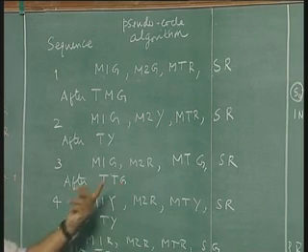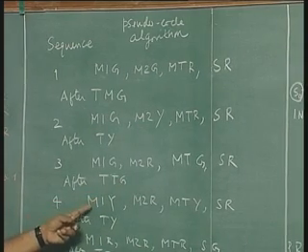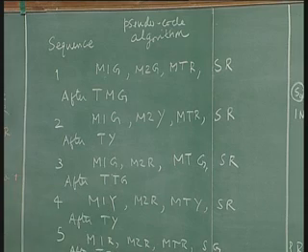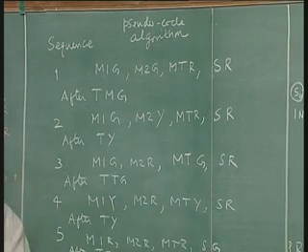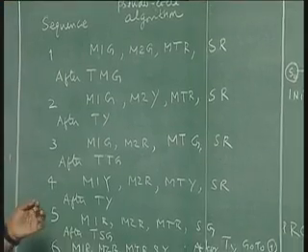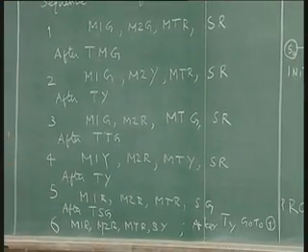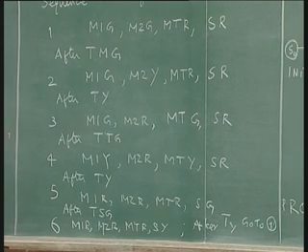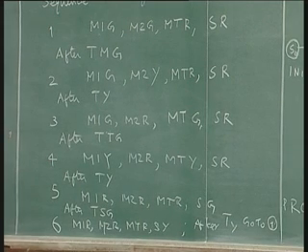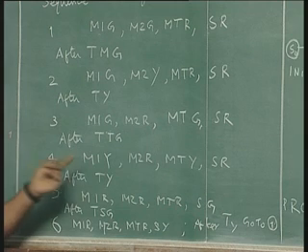After the elapse of TTG, I have main 1 yellow, main turn yellow. I am going to stop the traffic from left to right on the main state and also the turn traffic from main to side to allow the side to main traffic. In order to do that, I need to go through a yellow sequence.